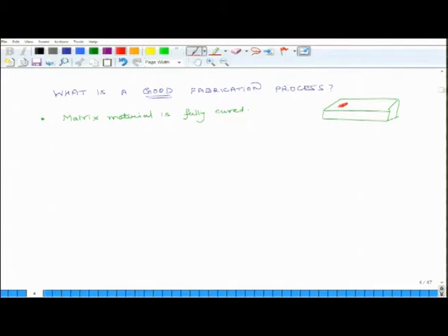Now, why could it not happen? Maybe for curing I have to apply heat, and as I was applying heat, maybe this area was not uniformly heated, it got heated to a lesser extent. So, the curing did not happen at the same time here. Okay? So, this part remained uncured. In that case, the properties of the structure will vary. It will be something at this place and something else at that place. That is not a good thing. So, this is one important reason.